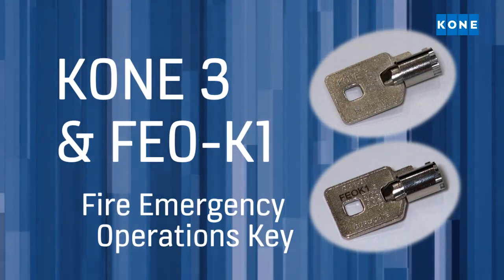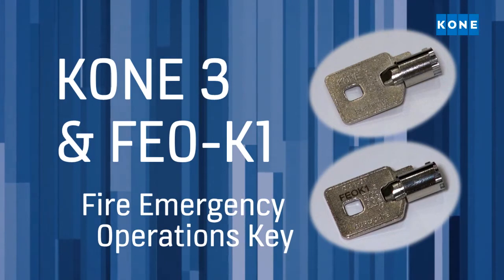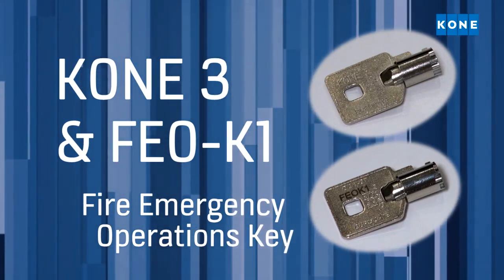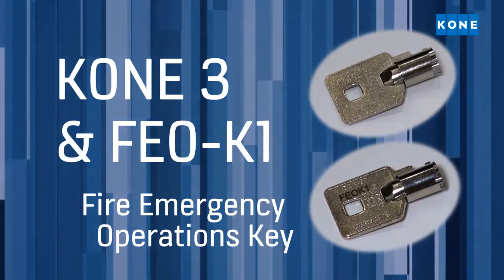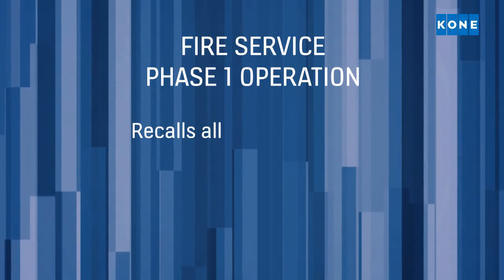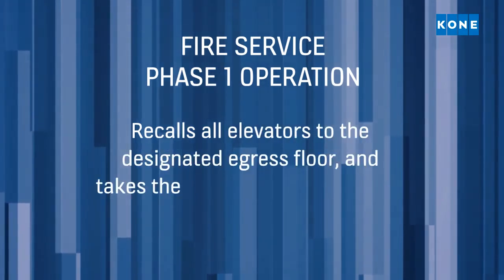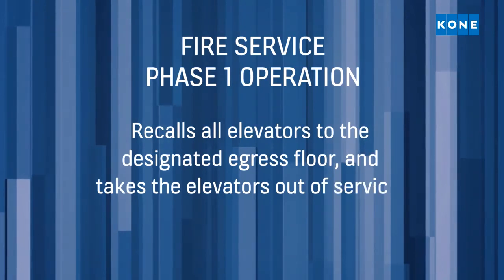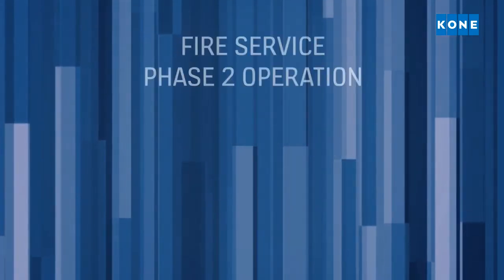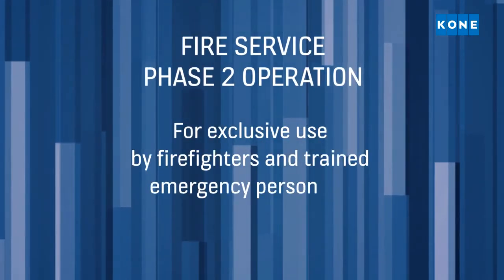Depending on local requirements, there are other possible labels for the fire emergency operations key. KONE will identify the fire emergency operations key switch based on those local requirements. Fire Service Phase 1 operation recalls all elevators to the designated egress floor and takes the elevators out of service so that they are not used during a fire emergency. Fire Service Phase 2 operation is for exclusive use by firefighters and trained emergency personnel.